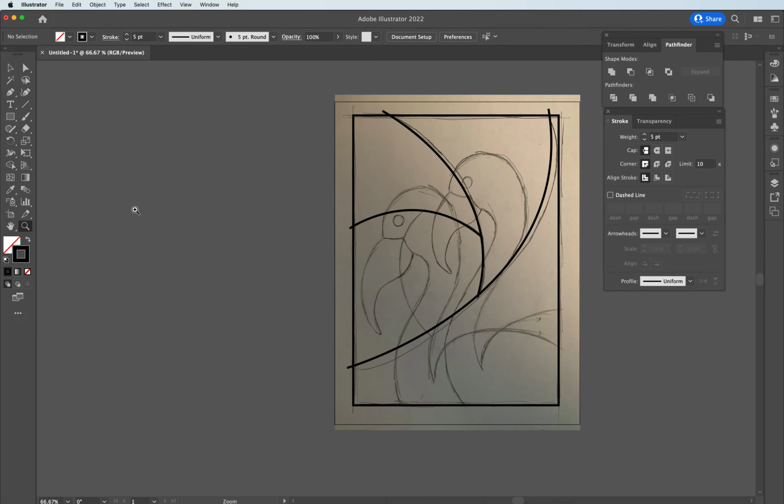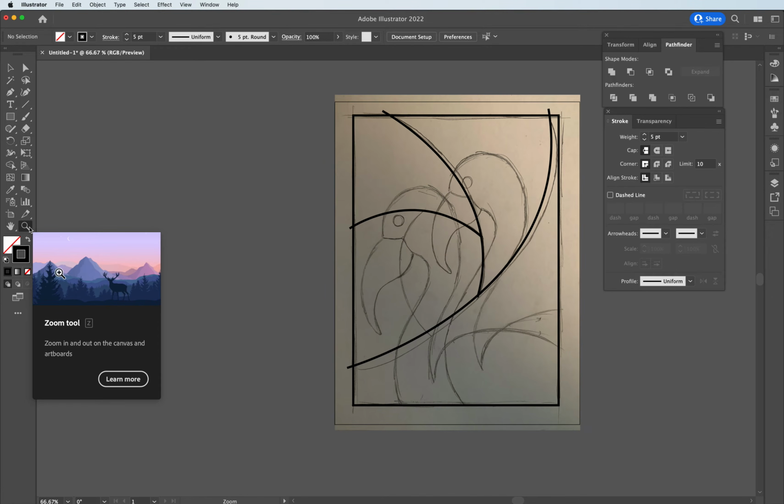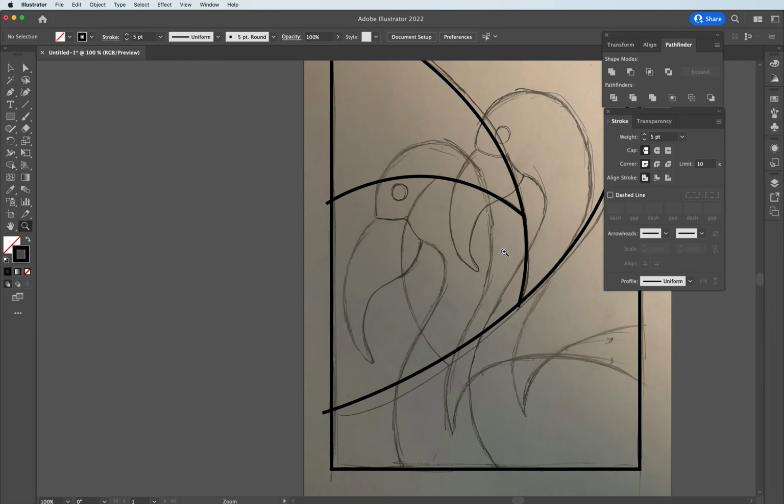So zooming back in, I can either use the zoom tool over in left side navigation or simply hit Control plus sign to zoom in on the area. Now I'm going to look to use this connecting line. I click a point, go down to where this third line was drawn out, and again draw out the curve as best possible to match it. I can hit escape and end the line.